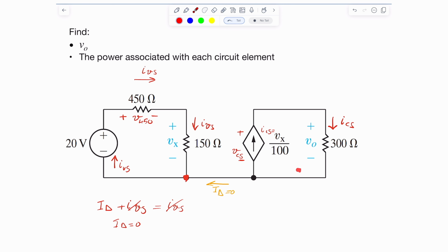So you might be arguing, why would we need this particular wire connecting these two parts of the circuit if they don't share the currents? Well, as it turns out, and you'll see it in electronics courses, this basically connects the ground, the 0 reference, because remember, every voltage difference is referential. There's a higher voltage and a lower voltage. In here, I'm saying the lower voltage, the ground, for example, the 0 for this part of the circuit should be exactly the same 0 as for this part of the circuit. If I say that the Vx is 5 volts, 5 volts here means the same thing. It's the same exact 5 volts. Okay, all right, so that's the point.